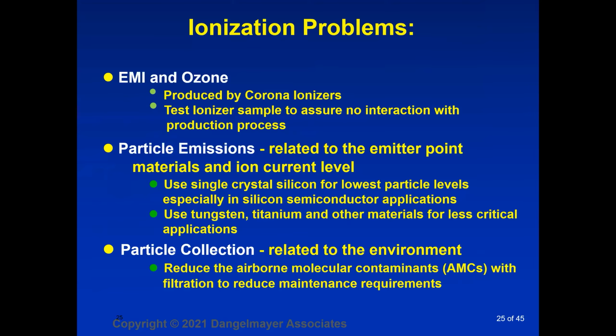So what are the ionization problems? Well, EMI and ozone first. They're produced by corona ionizers. Always test an ionizer sample to ensure there's no interaction with the production process.